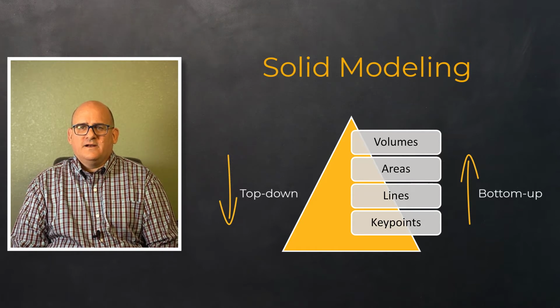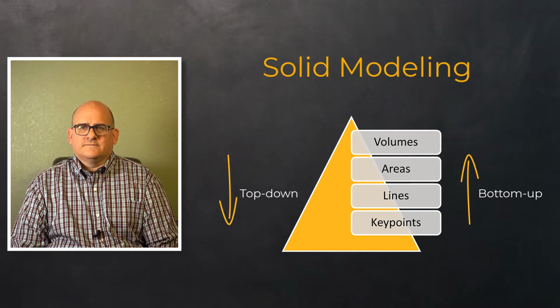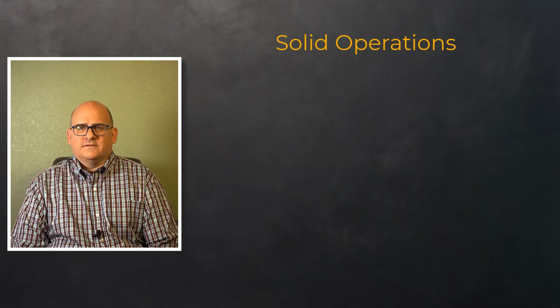Note that in a top-down approach, even though a high-order entity is first created, the lower-order entities that form it are generated automatically. While modeling solids, one can freely interchange between a top-down and a bottom-up approach. There are several solid operations that are available in mechanical APDL.